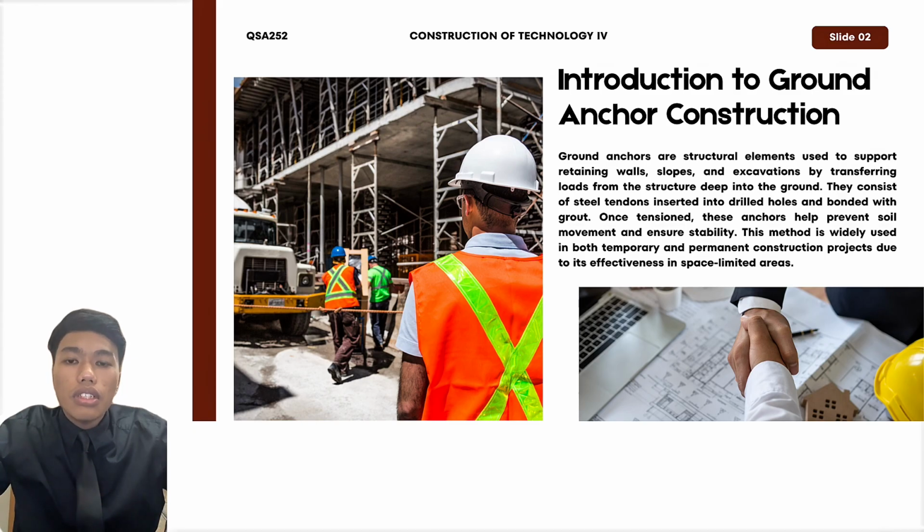Ground anchors are structural elements used to support retaining walls, slopes, and excavation by transferring loads from the structure deep into the ground. They consist of steel tendon inserted into drill hole and bonded with grout. Once tensioned, this anchor helps prevent soil movement and ensures stability. This method is widely used in both temporary and permanent construction projects due to its effectiveness in space-limited areas.